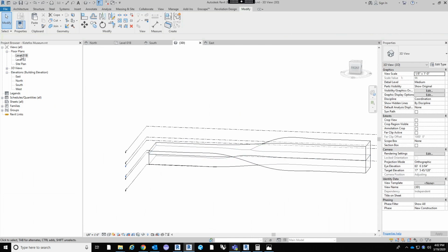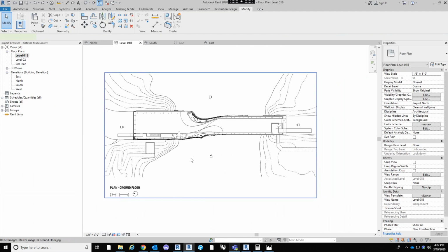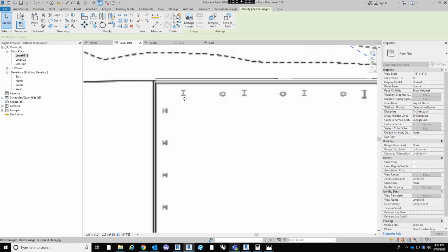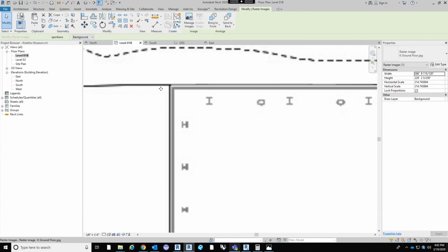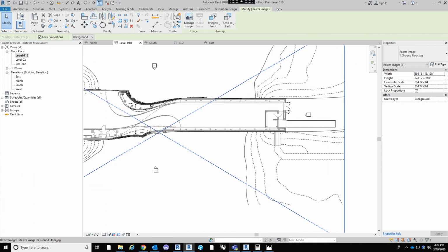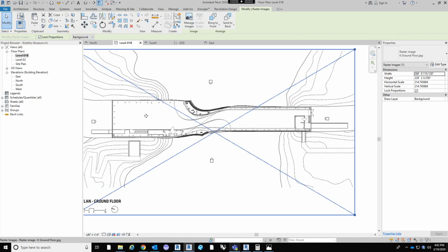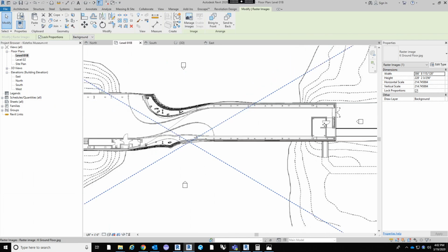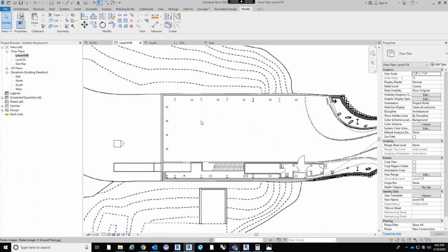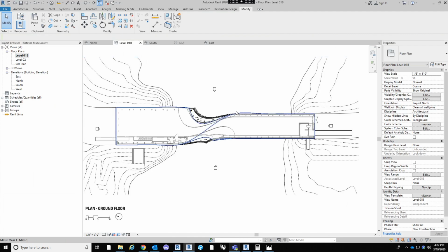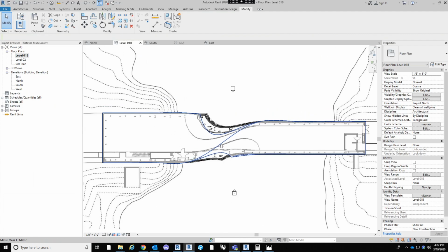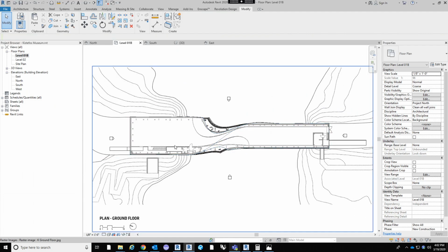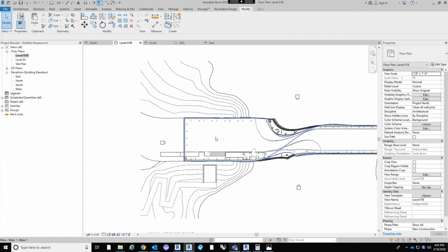Let's go into our level 1. Let's move this image so that it's actually in line with the mass. We can use our arrow keys to shift it over a little bit. Somewhat centered. Alright. And then what we can do now is create some structural. Oh, that's actually relatively close. Looks like the extrusion is a little bit different, but for the most part, it's pretty good, pretty decent.